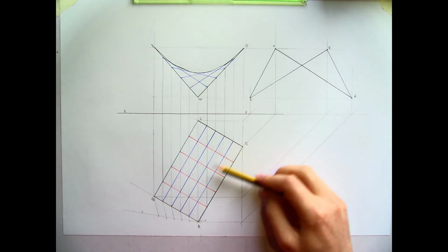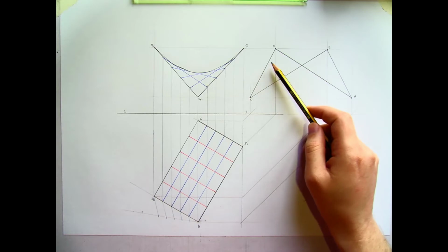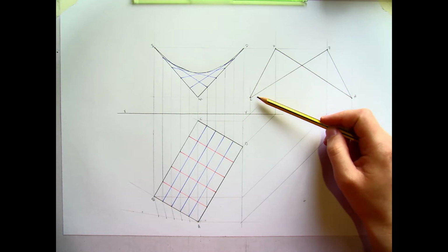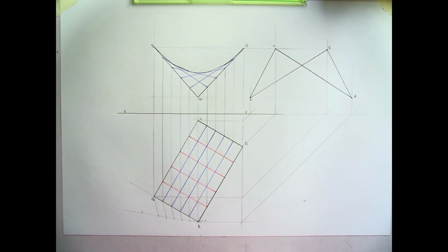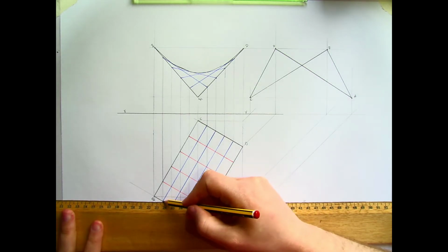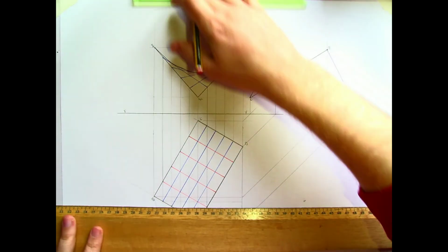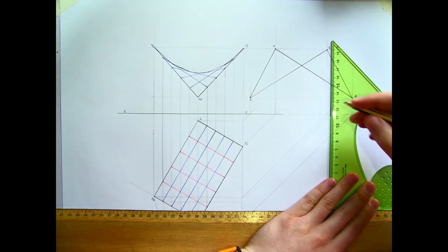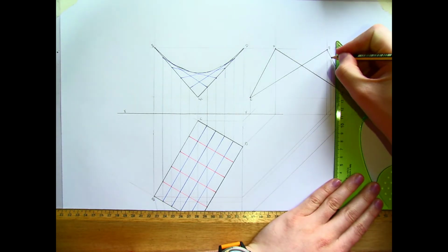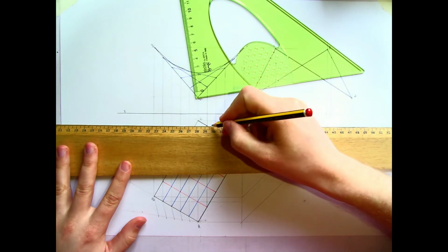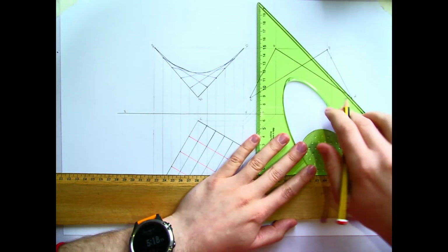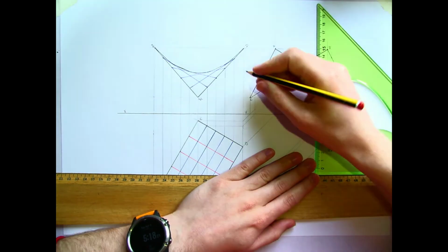So now each of the elements in plan and elevation need to be brought so that they appear over here in the end view. That's going to give us two curves, one probably going this way and another one up there like that. We'll see how that turns out. So I'm going to take the blue elements first. I'm going to bring them horizontal, up my 45 until it intersects with the line AB. That's one end of it. Same thing for the other end of it, except this time it's on the line CD. So that's this one.